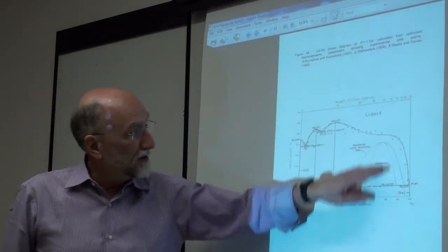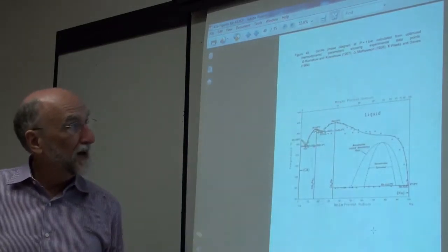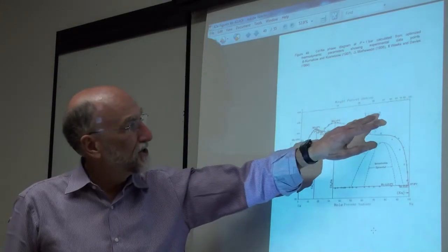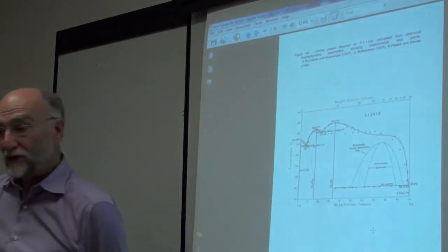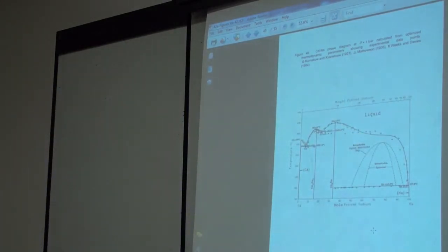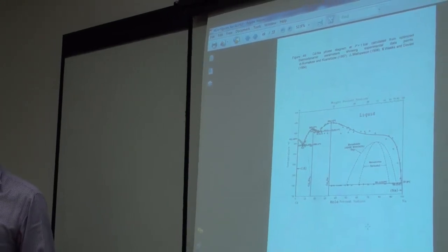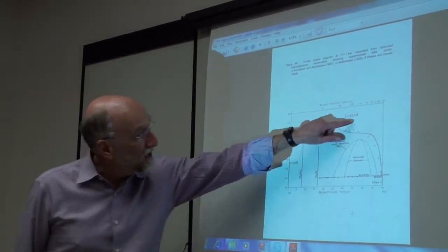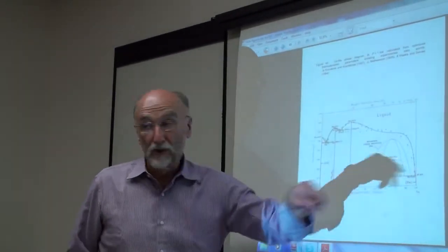Now, you could never suppress the solid fast enough. Well, if you suppress the solid fast enough and quench this down to room temperature at a very, very rapid rate by, say, splatting it between a couple of copper hammers, you could end up with an amorphous metal at room temperature, metallic glasses they call them. They're amorphous metals with metallic structure. If you did it in this region, however, you would find that there was a spinodal separation.